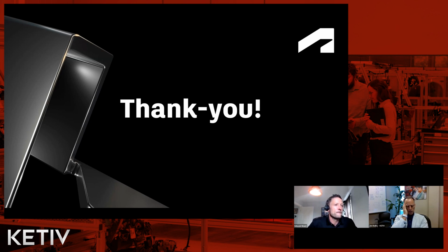Excellent. And then the other one is they want some further explanation, I think on the inclined flat. I don't know what in particular about the inclined flat, but I can talk about it from my perspective. Before that toolpath came out, you had multiple versions of flats. You had raster flat finishing, offset flat finishing, which only used to allow you to have a cut and then a final cut. Plus they weren't 3+2 5-axis capable.